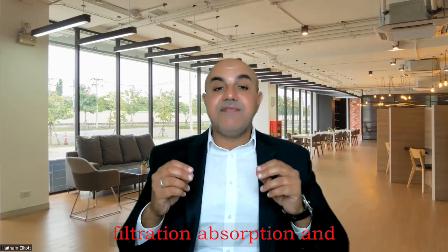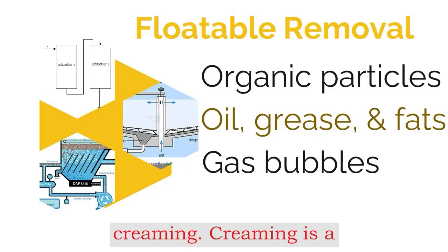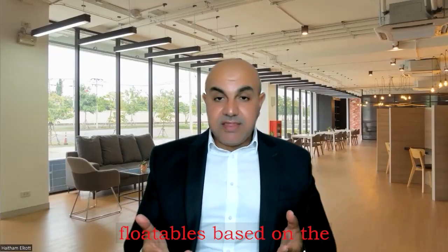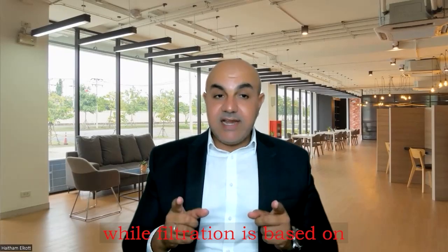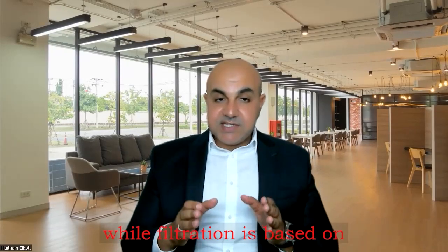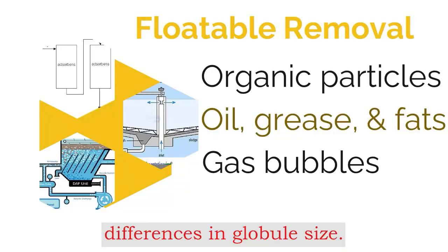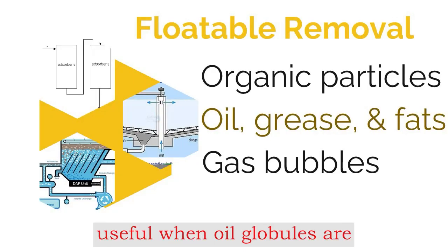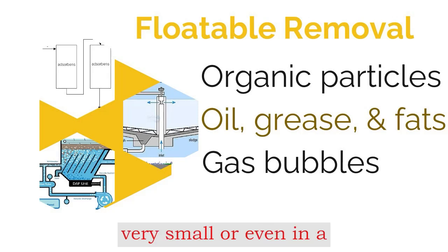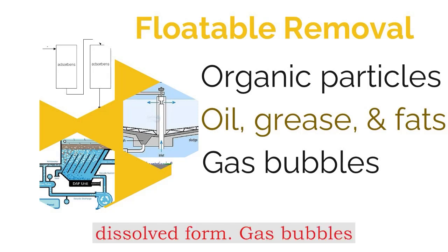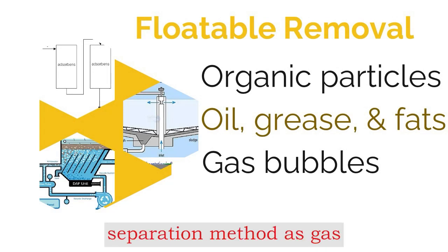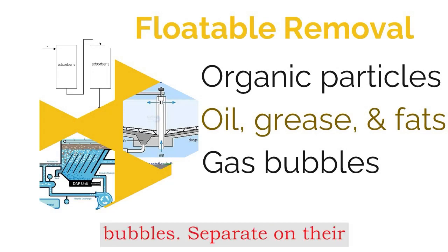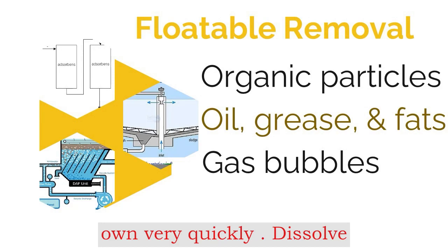Oil, grease, and fats. These can be removed through filtration, adsorption, and screening. Screening is a method of removing floatables based on the differences in density, while filtration is based on differences in globule size. Adsorption is particularly useful when oil globules are very small or even in a dissolved form. Gas bubbles. There is no need for any separation method as gas bubbles separate on their own very quickly.